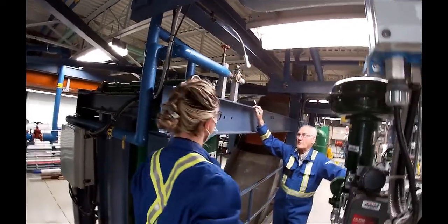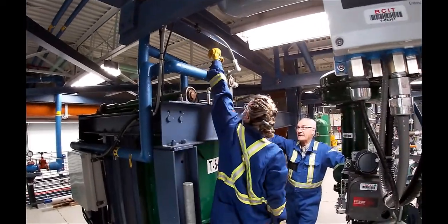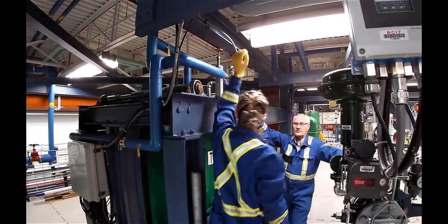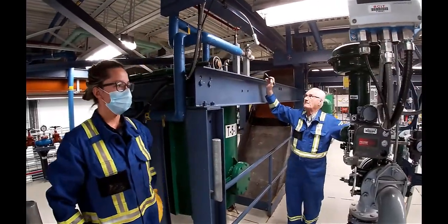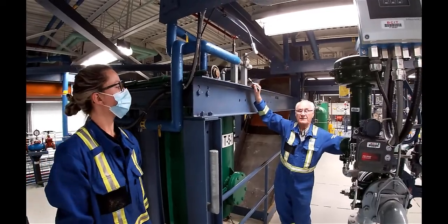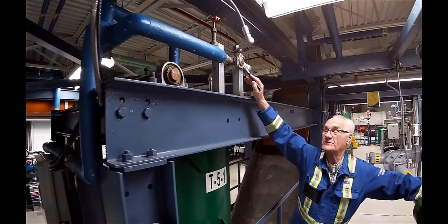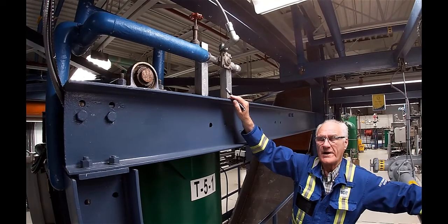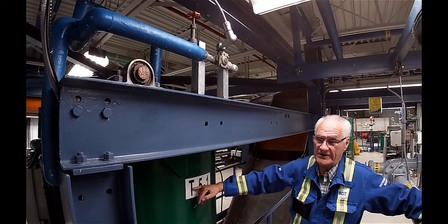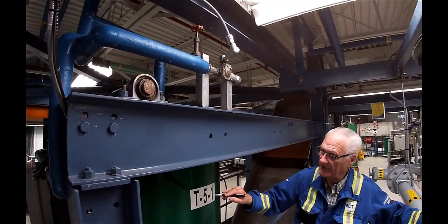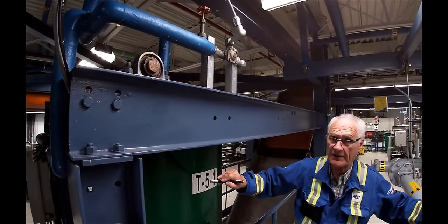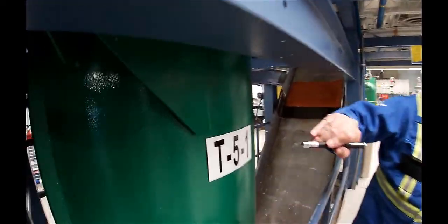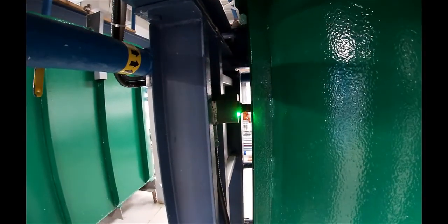Wide open and back a quarter turn. So the valve is the back seat. This is the solenoid valve, which, because we had that valve closed, is why the program did not proceed, because there was no increase in level in this tank. The tank is actually running on a load cell, and Ray, if you can catch the load cell itself. That's the load cell.